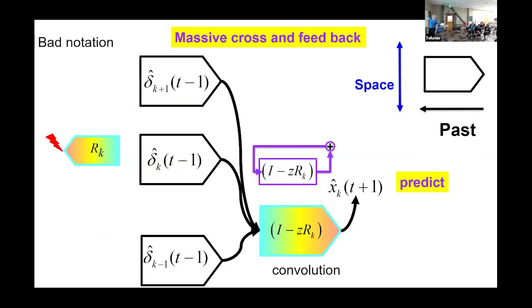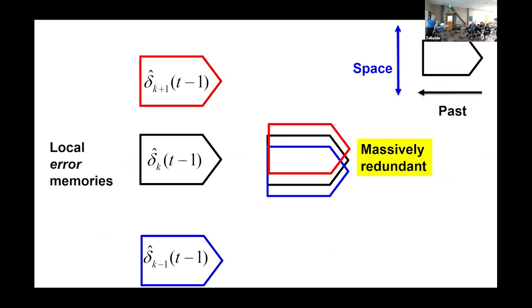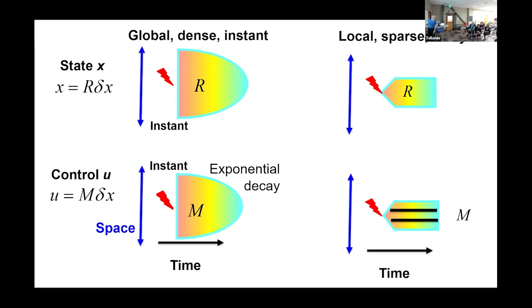What ends up happening is you have to keep a space-time picture of the past in memory. And then every time you update it, hopefully it shows here. Let me go back and say what this is. This would have been the global stuff. But once you design these things, that's a convex optimization problem, sparse here, dense here, but limited, okay? And that's what I want to do. It's a convex optimization problem to check the feasibility of this. If that's feasible, I know there's a controller K that I can get, and I can build it out of this, so K has the same sparsity as I imposed on the closed loop. That's why closed loop sparsity translates into controller sparsity in this direct way. That was a miracle. I don't know why I didn't think of that before, but I didn't.